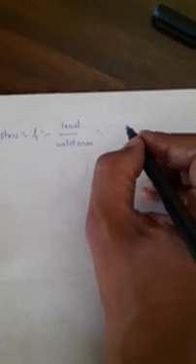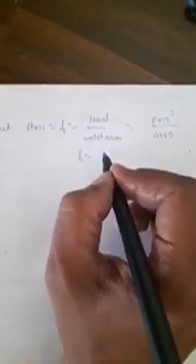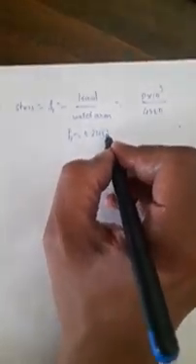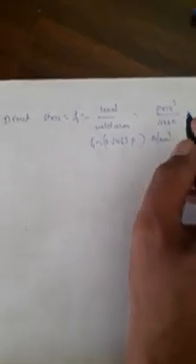So here we start. Direct stress F1 is equal to load divided by weld area. Load is P into 10 raised to 3 in terms of newtons. Weld area is 4060. So F1 works out to be 0.2463 P newtons per mm square. This is stress.